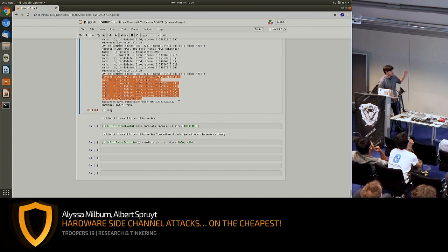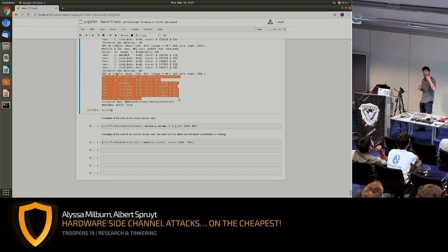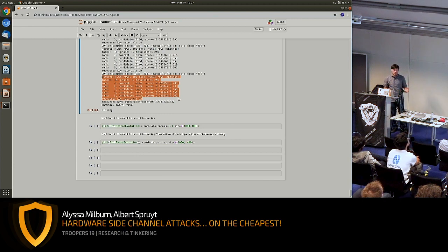We're now focusing on the last input byte, so the last key byte. And what we see is that Julia SCA has taken all these guesses and done the statistics on them. It's ordered all these guesses, which it calls candidates, basically by the score. The highest ranked key candidate has a score of 0.5, and basically all the others have a score of, let's say, 0.25. Which means there's a very large difference between this correctly ranked first candidate and everything below it. So this tells us with reasonable confidence that we've recovered the correct key byte.